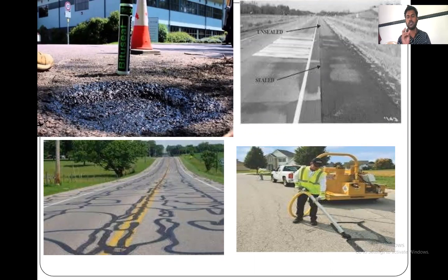Okay, if the dust and aggregates are there in the cracks, we need to first remove that material and make the cracks free from all dust. Then we need to apply the sealant. Mostly the bituminous sealant is used to fill the cracks.